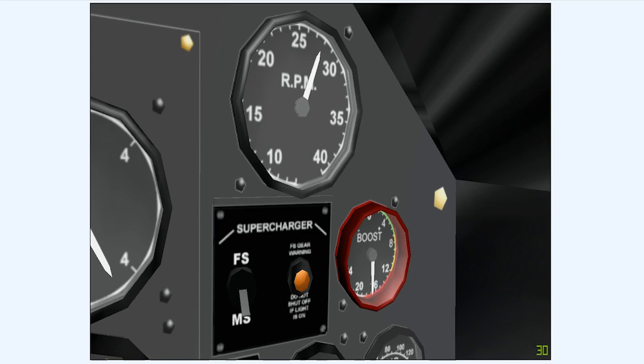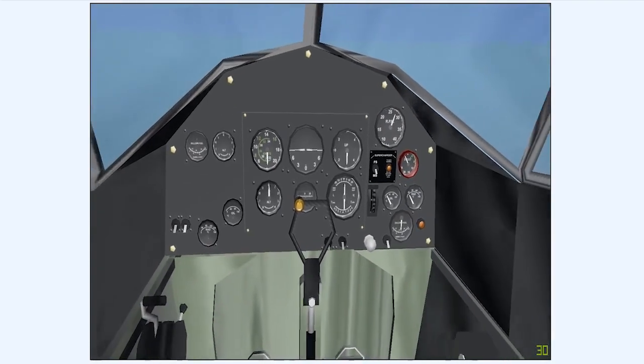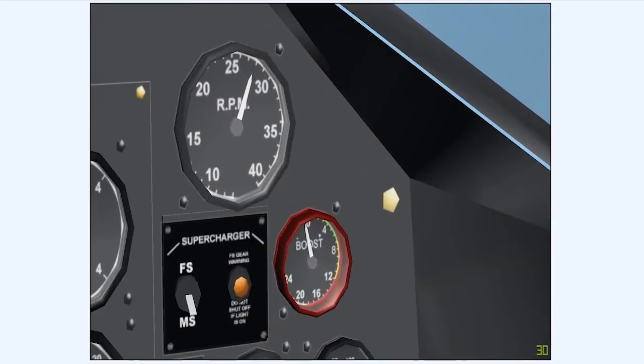There are two controls that affect the pressure developed by the supercharger. They are the throttle lever position, within the limits imposed by full throttle height, a term which will be explained shortly, determines the boost pressure that is delivered by the supercharger. The throttle is, in effect, a boost selection lever, and, together with the propeller control lever, determines the power output of the engine.